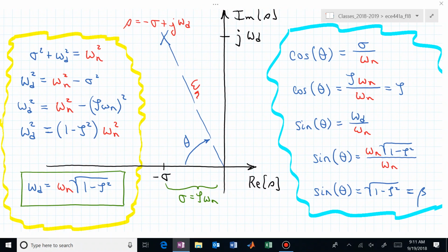So I think the way to look at this is to first not pay attention to what's in the highlighted space and just focus on the S-plane. The S-plane has one pole, and I'm just showing one quadrant, the second quadrant. That pole is an X, and it's at minus sigma plus j omega sub d. The real component is minus sigma. It's in the left half plane. It has a stable response. The imaginary component is omega sub d.